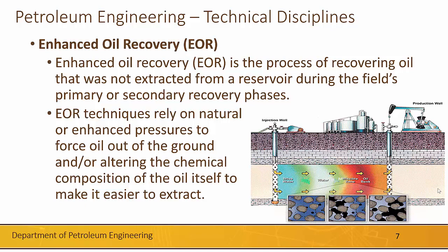This is a discipline that is used after the field has gone through its primary production and its secondary production phases, so the pressure within the reservoir has been depleted. Many enhanced oil recovery techniques utilize things like CO2 and polymers, which are injected underground into the reservoir in order to force additional oil out of the reservoir.